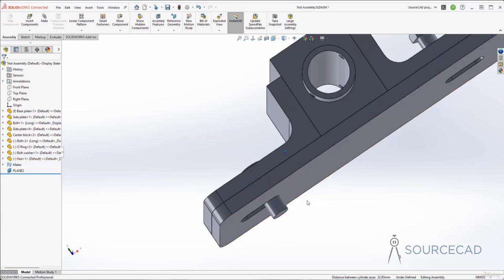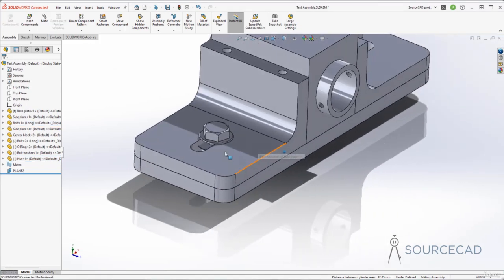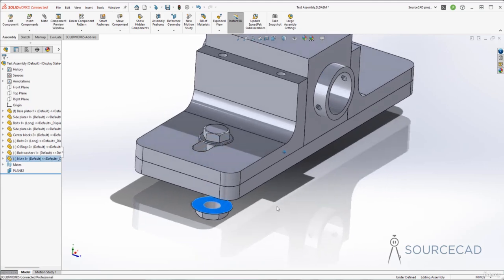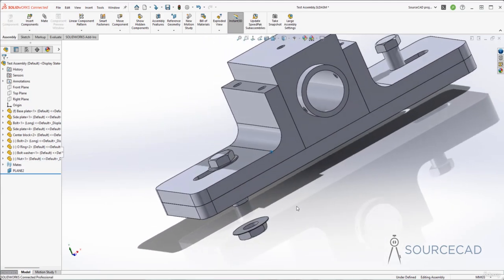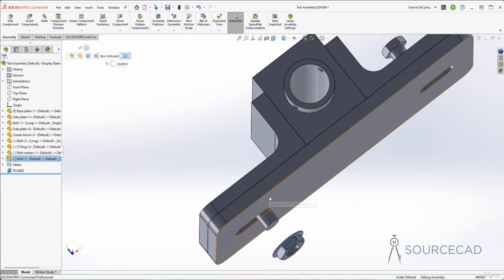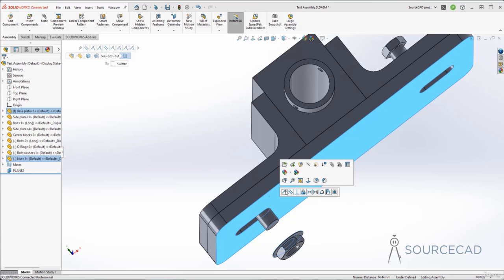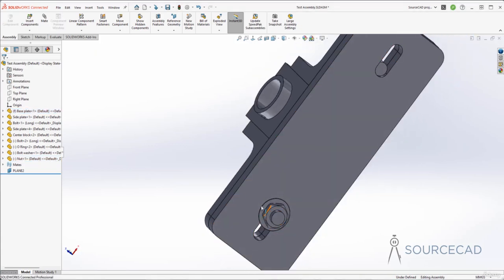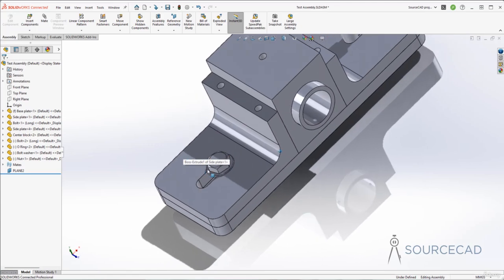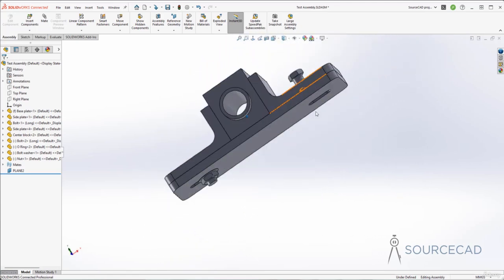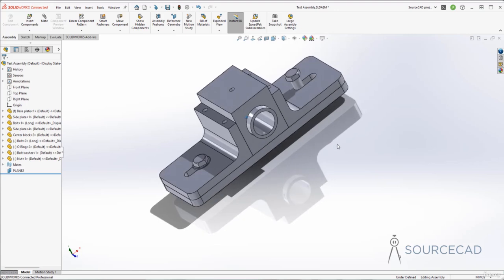All right. And we just need to move it down. And as you can see, it is stuck right inside this. So I'll just select it and move it down just like this. All right, and then I'll select this plane, I'll move it, and I'll select this plane, control select this, and just make it coincident. And we are done. So now this is added properly where it should be. Now in a similar way, we can add the washer as well as nut for this part, and I'll quickly do it.